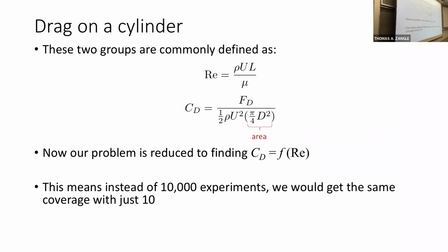The force of drag, this expression says, is 1/2 CD rho U squared times A. So for the same rho U squared times A, yes, it's proportional to CD. But we'll see that the coefficient of drag is a function of Reynolds number. So if you change U, then you also change Reynolds number, and there's some link between the two. But it is captured entirely by this functional form: coefficient of drag is a function of Reynolds number.